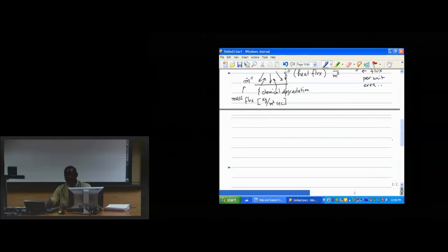Well, experience says that if you have a flammable material vapor, that alone obviously is not enough to create a flame, but it is the availability of this flammable vapor in an oxygen or an oxidizing environment with some pilot, as we would call it, some heat source that will allow the reactions to take place.